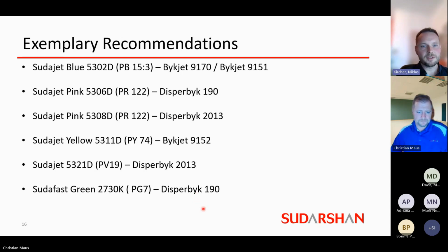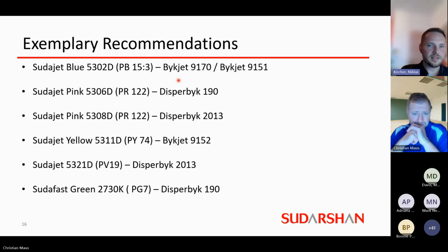I can tell you something about the dispersants mentioned here. We have the so-called BYK-JET grades that are additives that were especially developed for the use in inkjet inks. That means especially good viscosity reduction, especially good particle size reduction, and especially good stability. We are talking here about copolymers, SMA-based, so styrene maleic anhydride, is the backbone of the polymer.